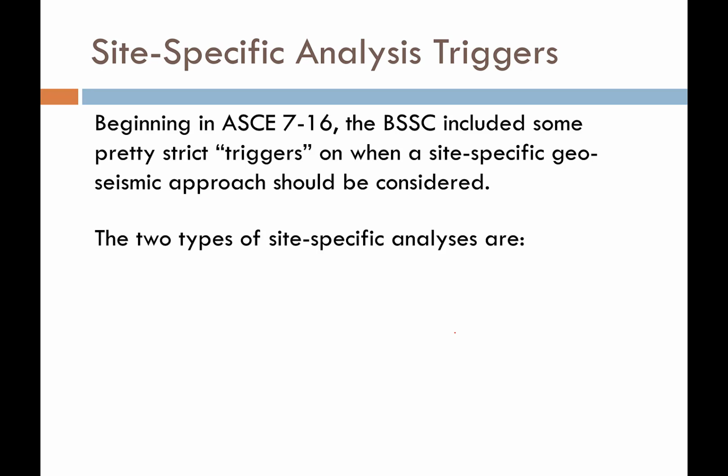And the two types, when I say site-specific, there's really two types of analyses that I'm referring to, and they're different. They're not the same. The first analysis is what's called a site response analysis. And this is where we're going to account for how the soil is going to amplify or de-amplify the bedrock ground motions. That's all a site response analysis is.